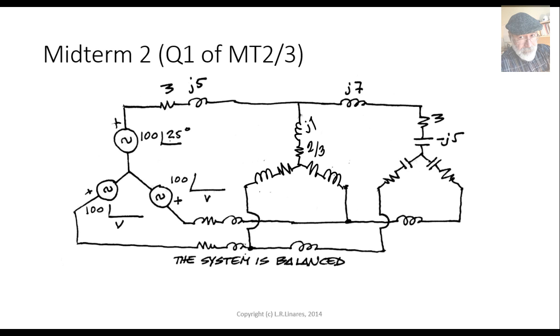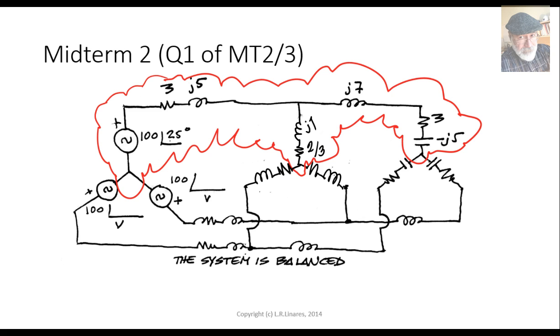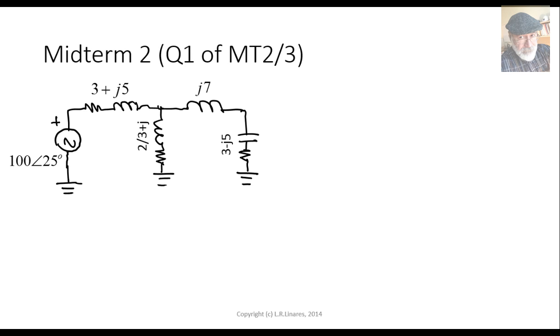Secondly, out of symmetry, the voltages here, there, and there, that is the voltages at the centers of all the Ys, are the same. Electrically, they are at the same point. So that's why I can solve only this part of the circuit, separate it from the rest, a single phase equivalent. And that is what I am about to do. Solve that circuit. Well, the first part is find the power in the source. How to do that?